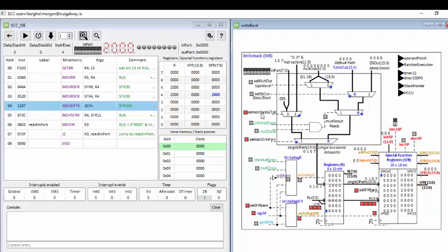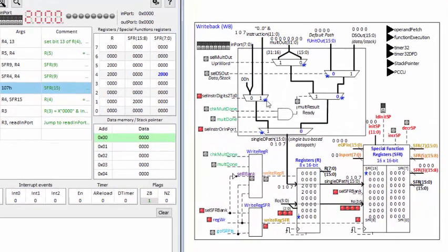Because the signal select instruction digit 2 to 0 is asserted, this path is selected. Select instruction or import signal is asserted. It puts the value 107 through to here for the register write. But this is being written to the special function register, so select SFR bank was asserted by the instruction decoder, as was reg write, so it goes to this bank.